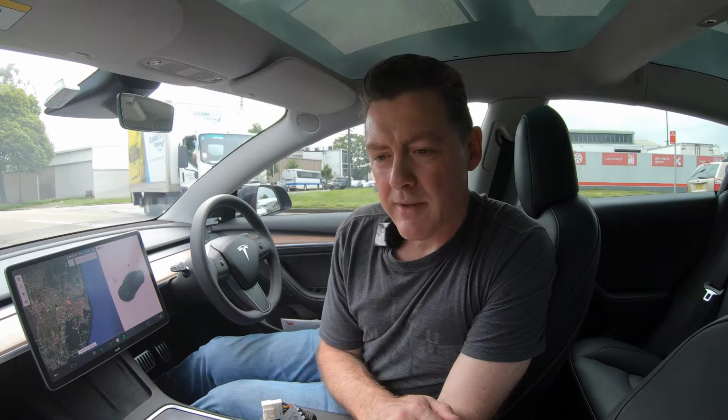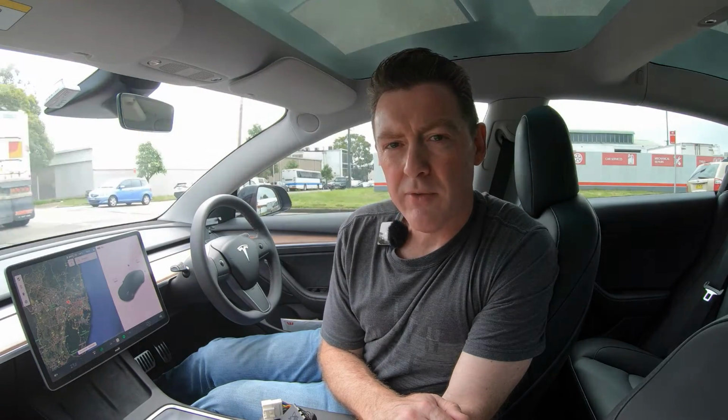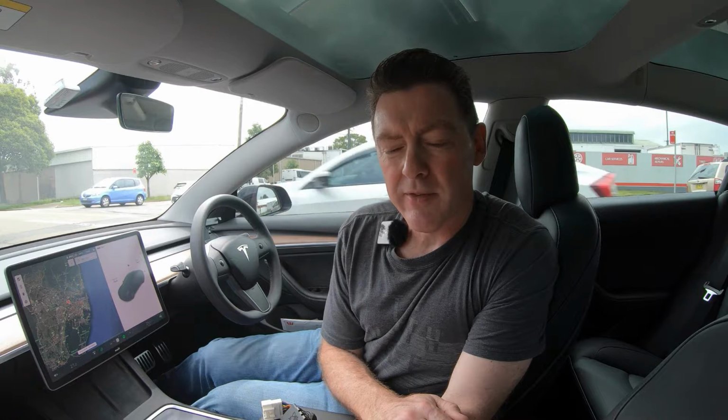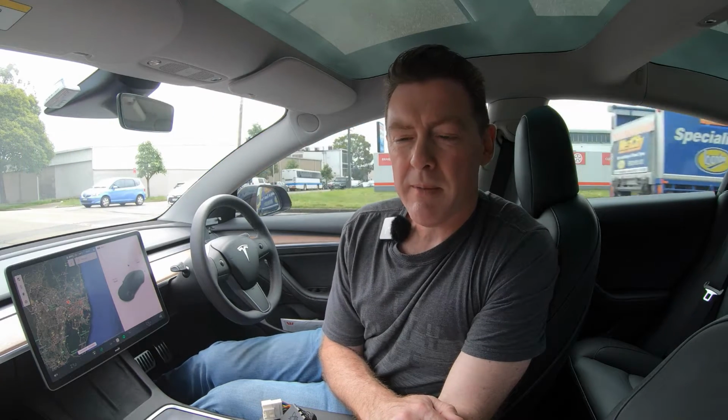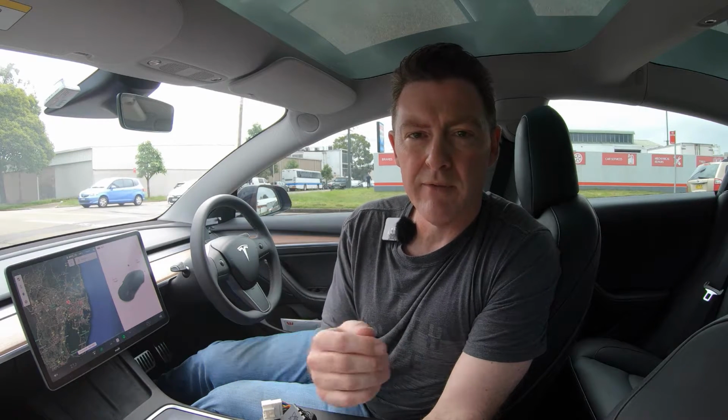So you have this signal being sent across 2 wires in the car. Now with CAN bus, you've got 2 wires that create a network throughout the car. And you have all this data flowing through at a very fast, very regular rate, and you've now got 2 wires sending all this information instead of 1 wire from every little switch and sensor traveling from the front to the back of the car. So CAN bus really simplifies things and reduces the amount of wiring.